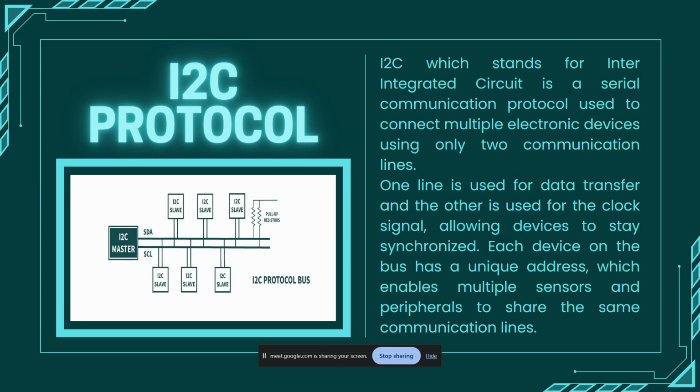So yeah, I2C protocol. It stands for, sorry, inter-integrated circuit. Stupid name, I agree, but we have two signals. First one is SDA, second one is SCL. SDA is the data line, SCL is the clock line.